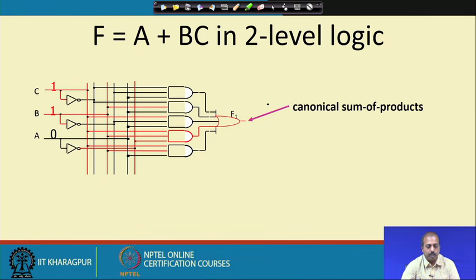Similarly this F 1. Suppose this A, B, C, the A is 0, B and C are 1. So, this is the situation, the F 1 output is equal to 1, and now if there is a change that B and C become equal to 0 and A changes to 1, then due to the delay, the effect will not come immediately. So, F 1 will be remaining as equal to 1, and now it will become equal to 0, and then after some time, suppose this inverter of B changes its state. So, it is getting 0, and it will affect the circuit after that.